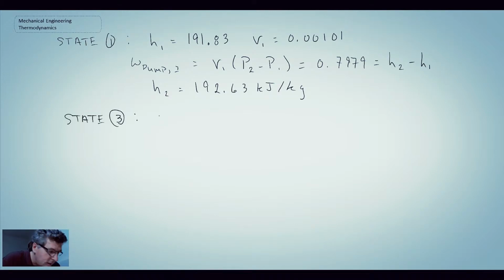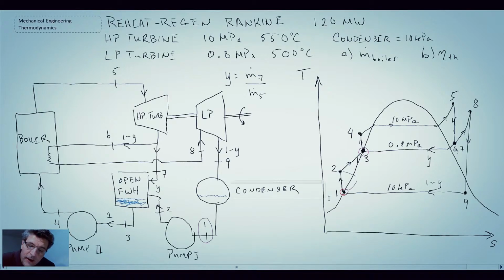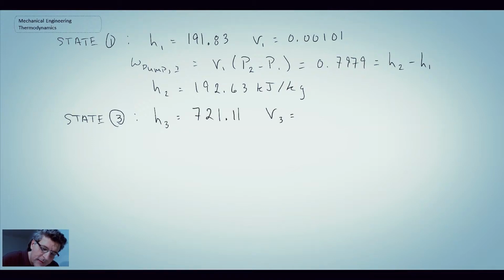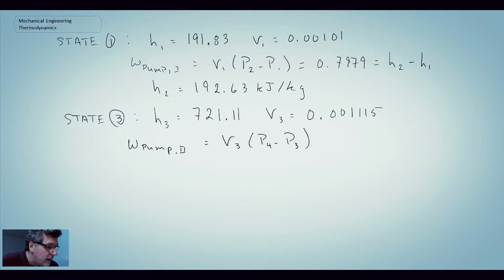We're just going to use the same process that we did before. The pressure for this one is the pressure at which we're pulling the steam off as part of the bleed stream, looking back on our TS diagram. That was at 0.8 megapascals, so that is the pressure you need to look at when you go into your steam tables. Again, we'll pull off the specific volume because we're going to use the work equation again to determine information at state 4, except here we have the pressure difference between states 4 and 3. We know H3, so we can directly determine H4. H4 turns out to be...